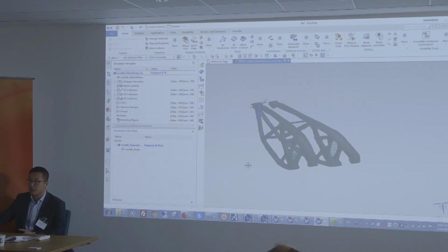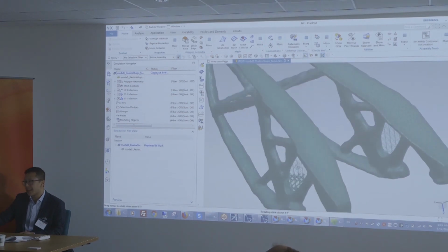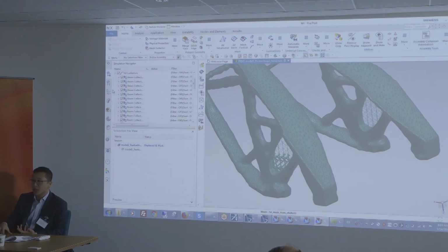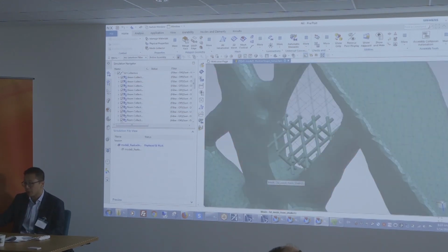Is the lattice mesh represented by 3D modeling techniques? So the lattice, yes, the lattice mesh is represented using 1D beam elements. So it's essentially a 1D connection element with a cross section that's tied and spidered, if you wish, connected to the 3D model.